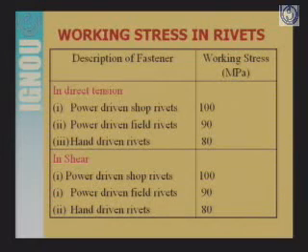Code also specifies working stresses in rivets. Here in this table, for two cases only, these working stresses are shown. First is direct tension, and second is shear. So I have shown you here the part of the table. The full table is given in your IS 800 code.